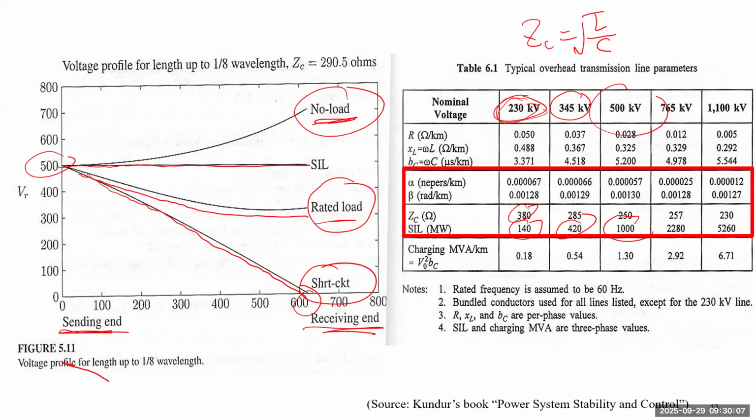But usually when we define the voltage level, we don't just check the loading, like the nominal load. There are many other considerations. So when you operate at very high voltage, for some conditions you don't have to power this much load. You may only power a load much less than this value. So for a high voltage line, you are more likely to see some overvoltage issues, if your load is lower than the surge impedance load.